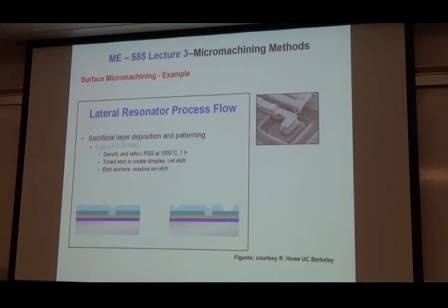So what I do is one more lithography on the PSG. When we say lithography, it means now I'm going to deposit a positive photoresist. I'm going to expose it with a mask, and that mask is called the dimple mask. So it only has this feature around here. Actually I'm doing 2 things. The first one is I create a dimple. So I do the first photo mask, expose, and then etch the spot, and then do not remove the photoresist yet.